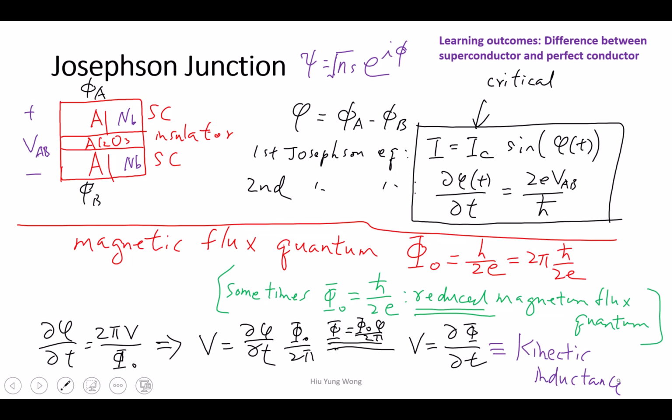So we never discussed this in our E class. But when you go to superconductor, this one picks up. Even this also has a regular inductance, because any object that has a shape has an inductance, right? You just do an EM wave simulation in HFSS. You can always extract the equivalent inductance. But it has a larger inductance due to kinetic inductance.